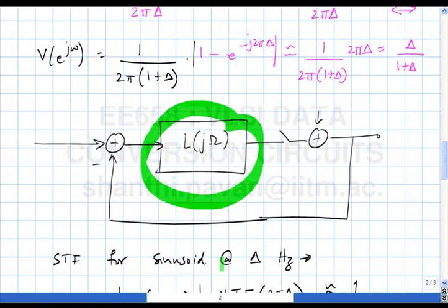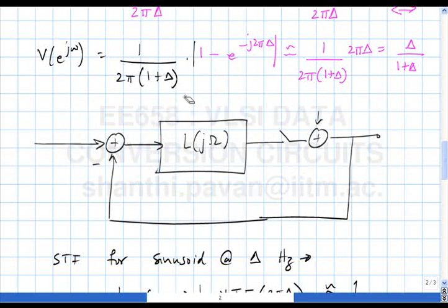Okay, it comes about. There's this whole area of control systems called discrete data systems, and the origin of these things happens because a lot of times in control, a lot of this control is applied to chemical plants. The plant has valves and all sorts of complicated looking stuff, but the control is best done numerically. So you have a computer which goes on looking at the various outputs, in other words, the various states of the chemical plant, and applies appropriate control inputs to make sure that the chemical plant is running as it's supposed to do.